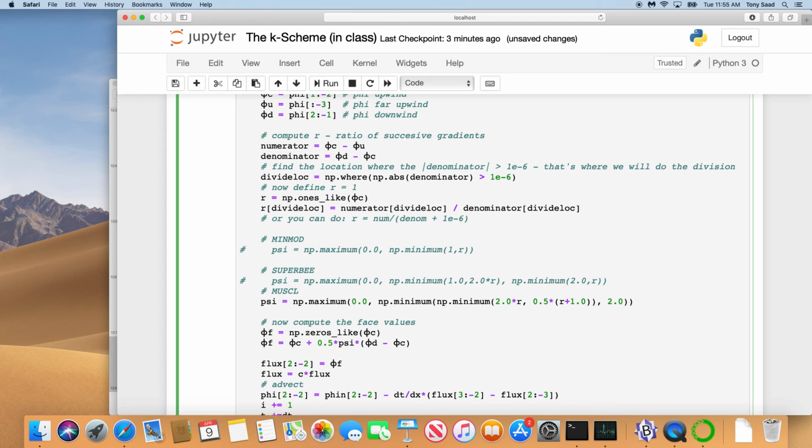There's a lot of literature arguing about the order of accuracy for these schemes. Are you really truly second order, or are you first order? Since we're combining upwind and second order, the first order error is probably going to dominate, unless you're limiting that first order error to a few points in the domain. How is that going to behave as you converge your solution? Those are all interesting questions to look at.